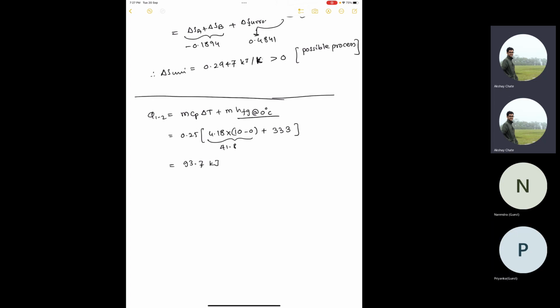2501, essentially it says when you want to convert liquid water at 0 degrees Celsius to vapor at 0 degrees Celsius, but I don't know that that state of system is feasible or not. So anyway, the moral of the story is if there is ice involved, don't use steam table.